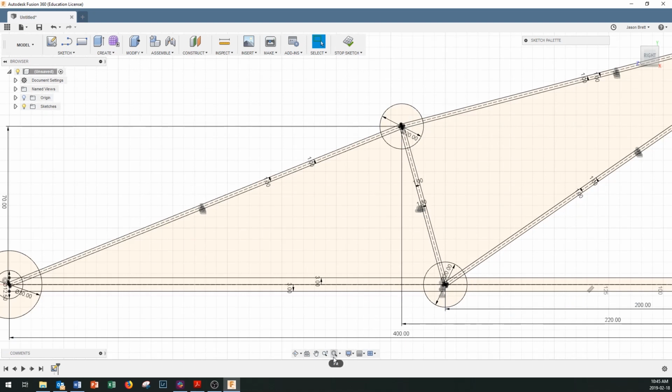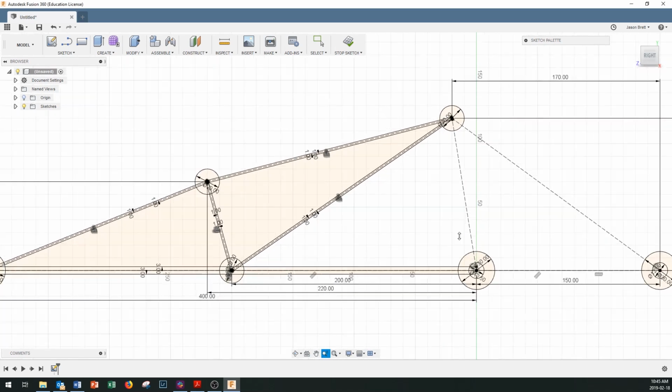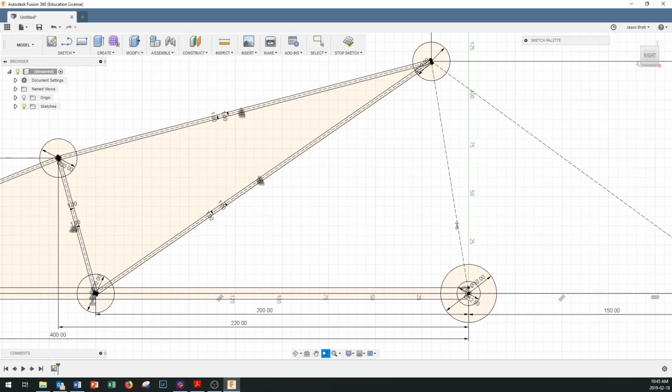And let's see right here. Let's zoom to the whole thing. I wanted that to, oh, there we go. There's our zoom to fit. Okay, this one coming up and down here is probably going to be under some of our heaviest compressive load, and it's a fairly long member, so O for offset, and we'll set that up to 4 millimeters.